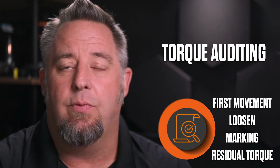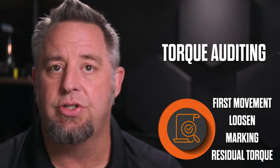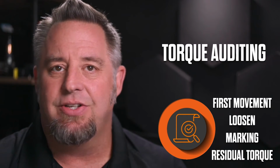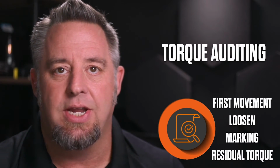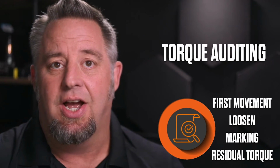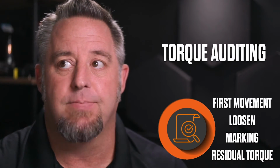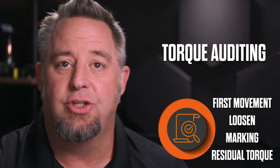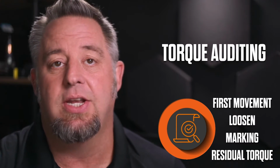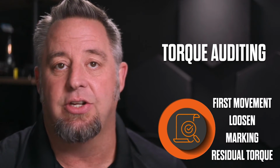The values that we would be seeing at this point are going to be somewhat close to the actual torque value that was delivered, but because there are a tremendous amount of factors that go into the actual torquing during the process, that value is going to be different due to factors of lubrication, could be speed, the type of tool that was used. So a lot of those variables that go into the actual delivery of the torque value are going to be a little bit different than what we would see during the test.